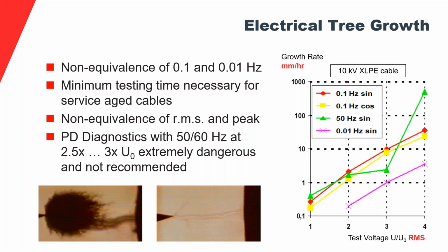Then they pretty much found that 0.1 Hertz is okay, 0.01 Hertz or anything below 0.1 Hertz is not. And also very interestingly, right now the CIGRE working group that is extending these testing specifications or these testing rules into the high voltage cable world, they also, as far as I know, it's not really finalized yet, but 0.1 is the threshold. Slower is a problem because then you get into other issues. So they recognize 0.1, but nothing slower.